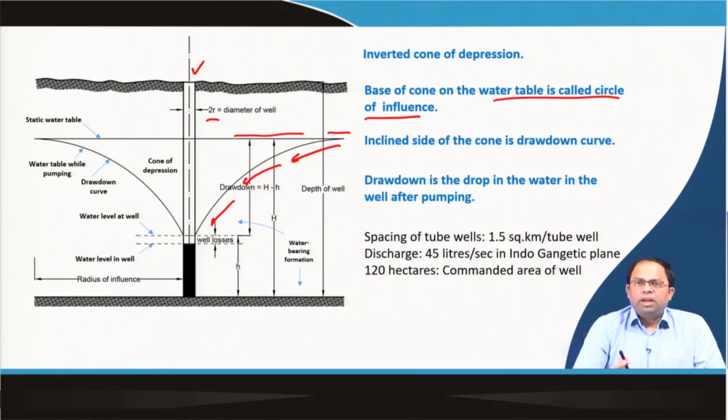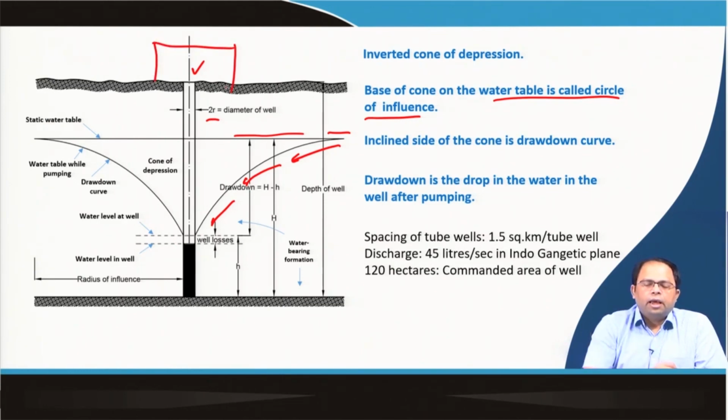This has a lot of implications, and I will tell you why. Suppose you have a real estate project, for example a housing colony, and you have put in a deep tube well over here, and you are drawing water from here. As soon as you are drawing water, the surrounding water table is bended, and during the time water is entering this particular well, the water table will be bent like this. Now, suppose these people are drawing water from a depth of around 300 meters. So, it is a pretty big deep tube well.